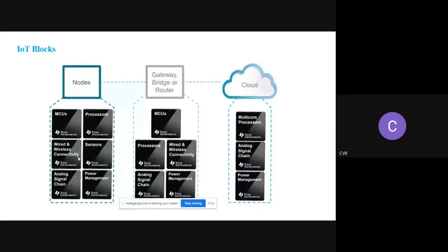Sometimes you may get a false trigger. For example, with sensors in automotive, if the temperature varies, then your output also will vary, but you need to consider those things and correct it in the software. So you need to know the behavior, and how the errors happen in the ADCs and op amps, etc. All of these you need to correct. So you need to know both hardware and software. Okay, that's very important.